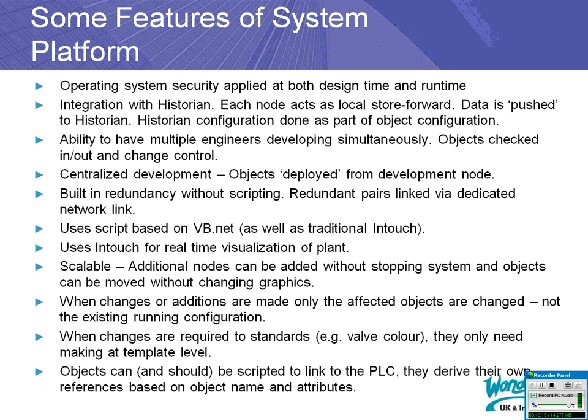Finally, a big thing about System Platform is you should script the objects to link automatically to the PLC. We talked about how, with System Platform, a lot of the work is in getting the templates right. They can derive their own scripts to link themselves to the PLC, so you just drag and drop, create an instance of that valve, for example, and it will know which PLC to link to, and link to that PLC. That's done via the script that's attached to the object. Now that can also be done for older PLCs where you may have registers instead of proper names. You may have to put a mapping file in that case,